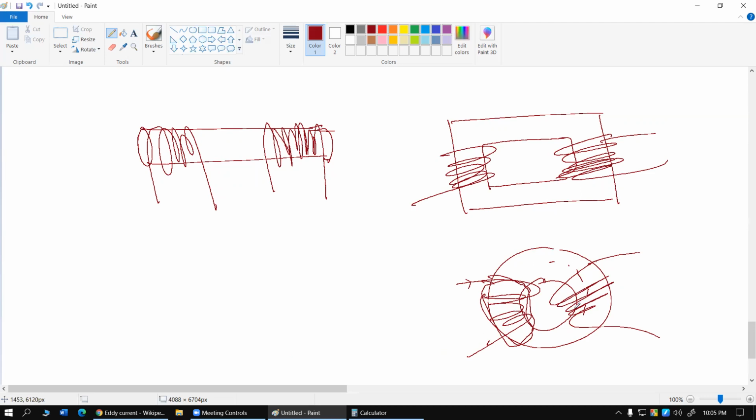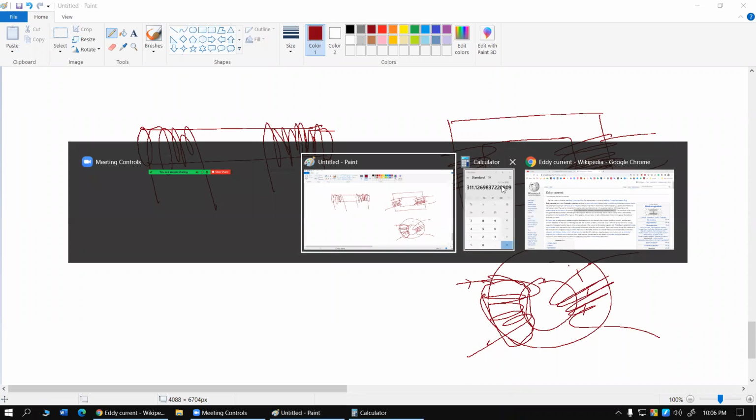That eddy current heats up the soft iron core, and if we want the transformer to run properly, we have to significantly cool down the eddy current. Typically, all the transformers that we have are dipped inside an oil bath, and the oil is usually cooled down by a natural convection process through fins and channels which exist outside the transformer body.